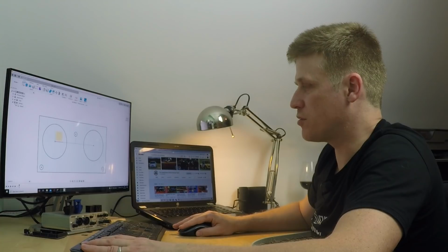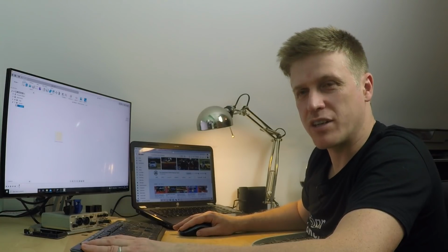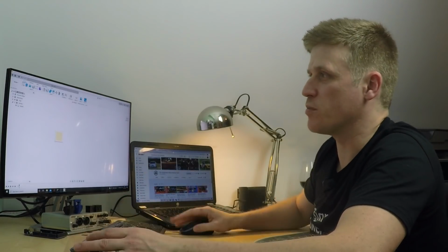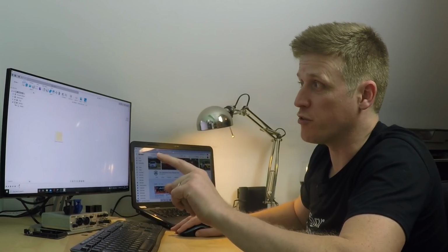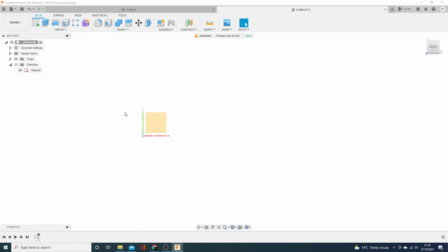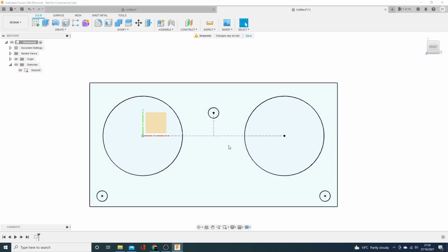So if you ever have something strange happen, like you click that and everything disappears, make sure you come over here, because of work I was doing on this before I started filming, I've got sketches turned off. So if I click them back on, that immediately comes to life. So what I've got here is a nice fully constrained sketch, because everything's nice and black.